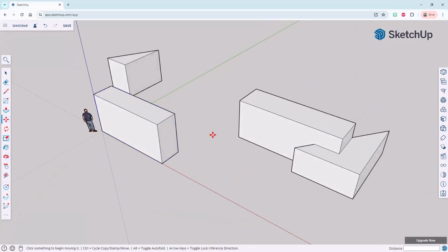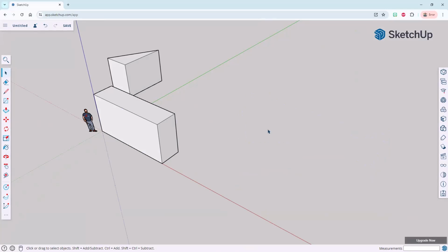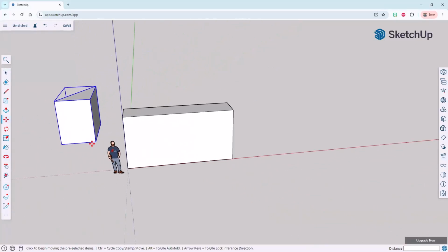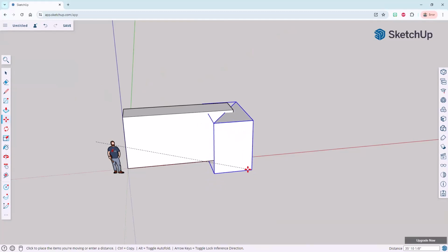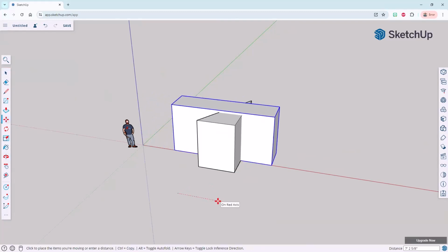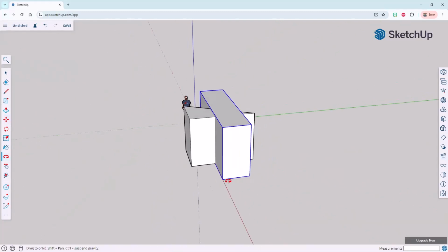And that's why every time you make your objects, and by the way, I'm just highlighting this and I'm going to tap the delete key, make it go away. Anytime you make objects, always group them. So now watch this. I'll take this solid over here. I'm going to move it from this endpoint over here and notice how they can intersect. See that? But they're not going to interfere with one another. I can take this rectangle and move that. And they're just kind of overlapping each other.